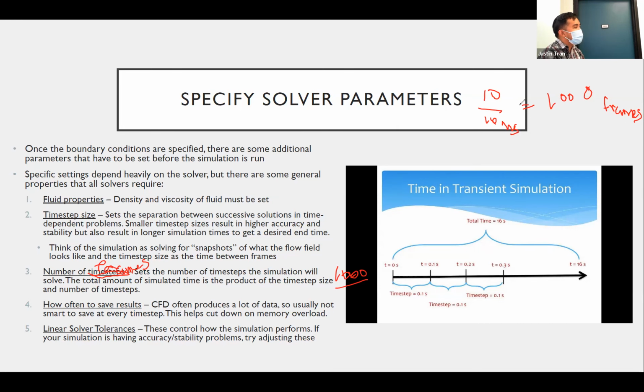And so that 16 million simulation I was telling you about, I saved it every single frame. It took up about how much was it? It was about 600 gigabytes of data on the cluster, and I got a very stern talking to by a lot of people. CFD produces a lot of data, and I can't really understate that. You want to be careful about how often you save your results, and think about how much is really necessary for you to perform your analysis.